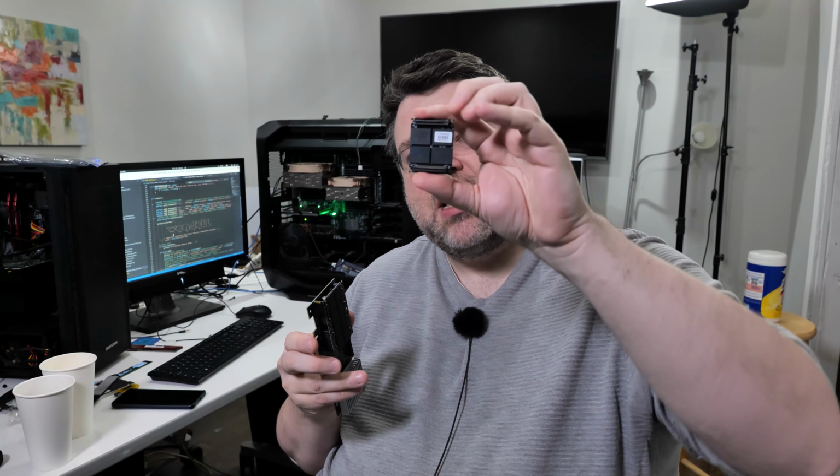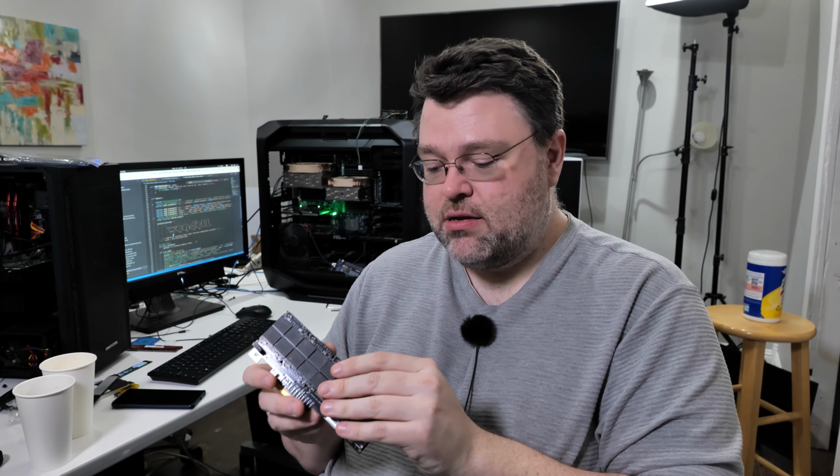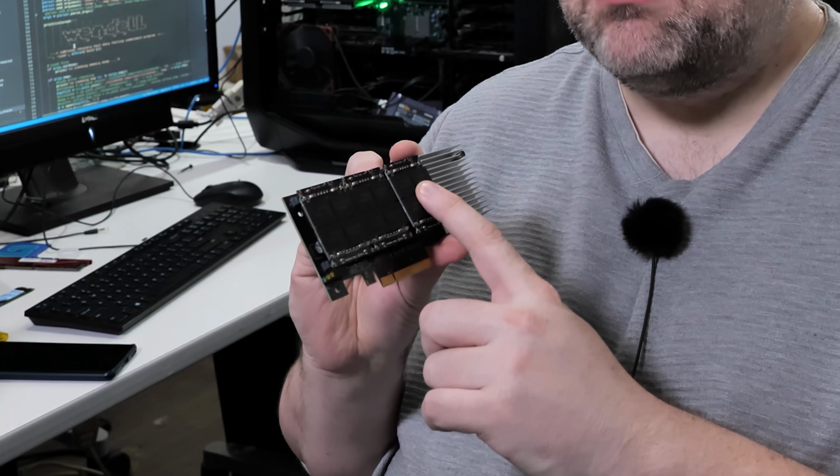But it's also modular. We've got 3 of these modules that are double-sided, each with 8 flash memory chips. And the 8 flash memory chips on here are 64 gigabyte Intel flash memory chips. Very, very well engineered, very well binned, very well hand-picked. 64 times 8 times 3, it's about 1.5 trillion bytes on this thing. It has a formatted capacity of just about 1.2 trillion bytes, a little less than 1.2 terabytes if you're counting in binary.